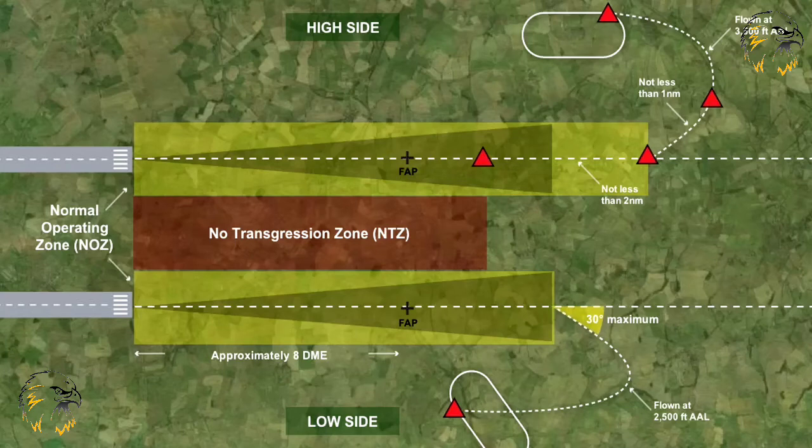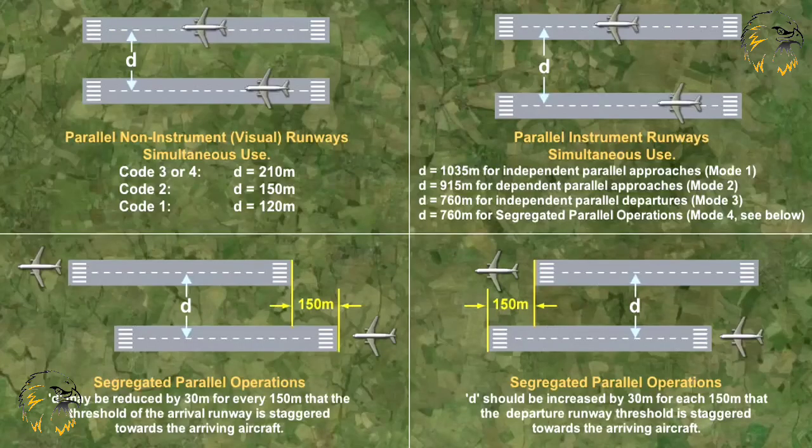Simultaneous parallel ILS or MLS operations require diverging tracks for missed approaches and departures. Turns to achieve divergence are to be initiated by pilots as soon as possible. When building runways for simultaneous parallel use, minimum spacing distances between the landing or takeoff surfaces are defined and illustrated here.